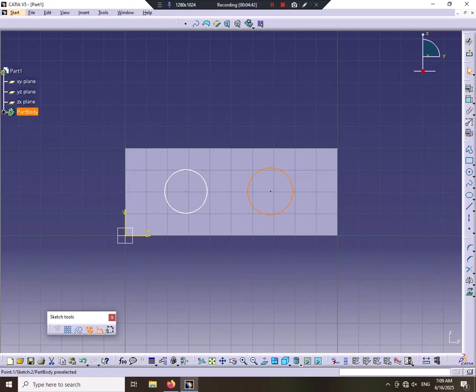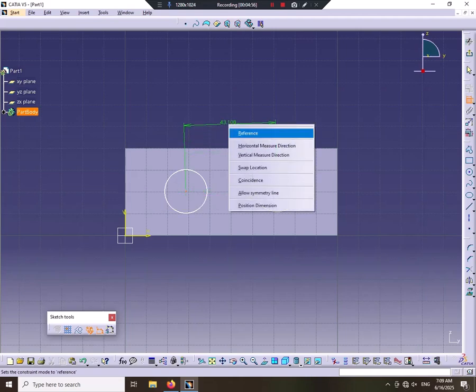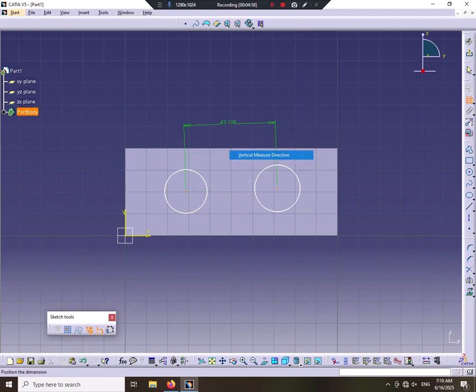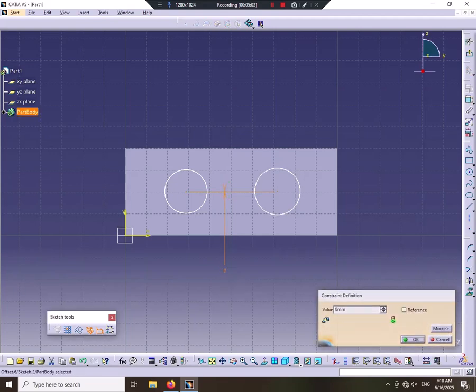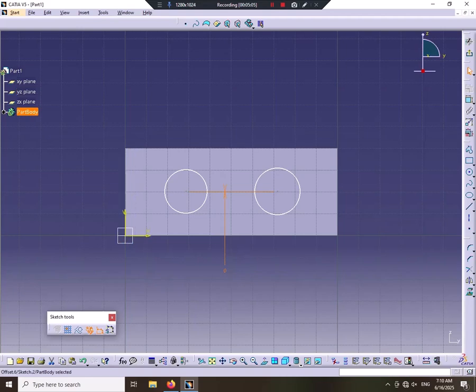This can be moved anywhere; it's fully free. One of the ways to limit its movement is to set a vertical constraint. If the vertical distance of these two is 0, sometimes it's horizontal, depending on where and how we design it. Now these two can move together because they have the same center.